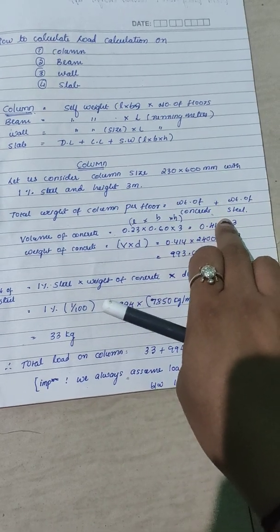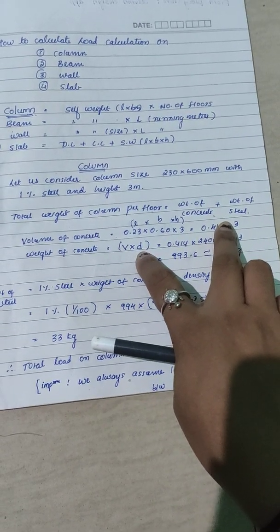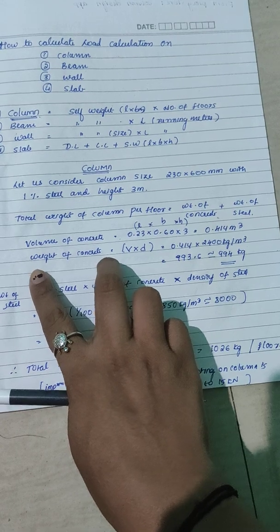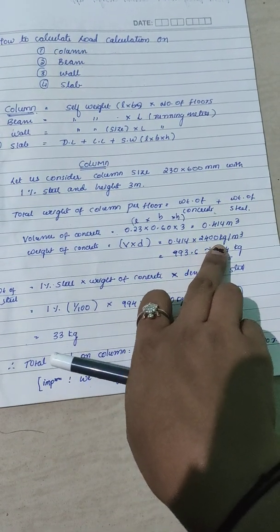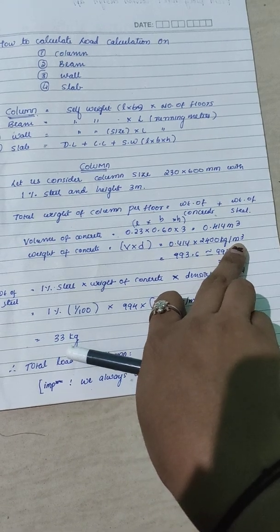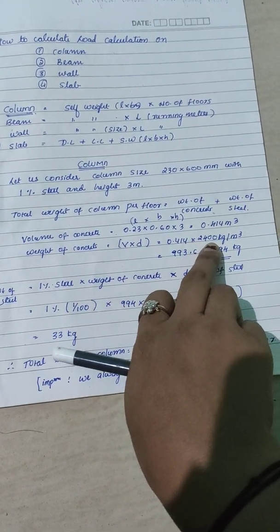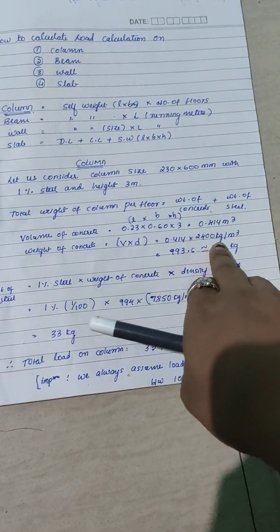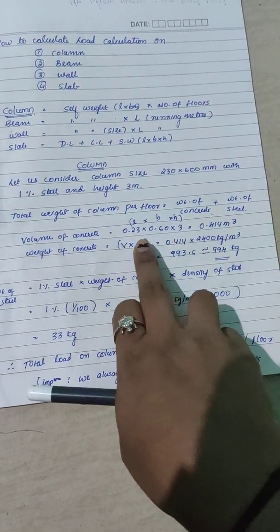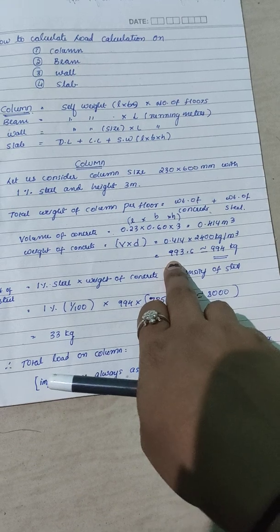When you multiply volume with density, you will get the weight of the particular concrete. Density of the concrete is nothing but 2400 kg per meter cube. This is for plain concrete. If you consider reinforced concrete, it is 2500 kg per meter cube. Okay, so finally we will get the answer as